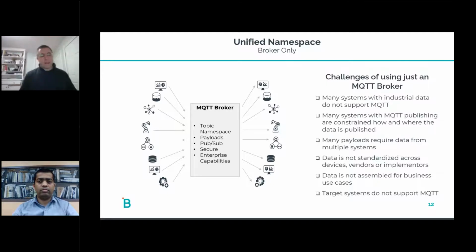It turns out that the raw data in many cases comes from the operational data from, say, the OPC servers or the process data. But in many cases, the context comes out of other systems like your CMMS or your MES system. So we need to combine the data payload before we place it into the broker.